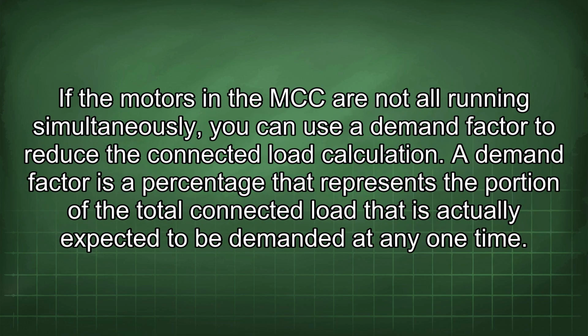If the motors in the MCC are not all running simultaneously, you can use a demand factor to reduce the connected load calculation. A demand factor is a percentage that represents the portion of the total connected load that is actually expected to be demanded at any one time.